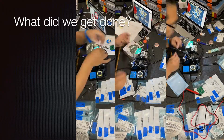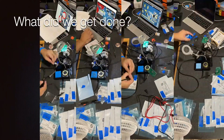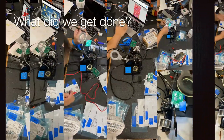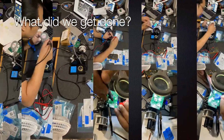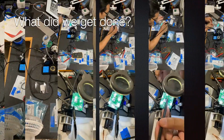When the PCBs arrived, we did some initial continuity tests on the PCB to verify each pad is connected to the correct traces. We were able to solder on every component except for our lamp for our transmitter, and obviously the part that is still in transit. Our ADC for the receiver circuit is not soldered onto the PCB. Keep in mind that these components are extremely small to minimize troubleshooting.